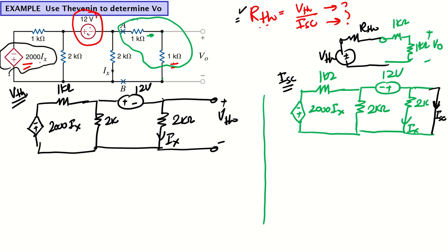Thevenin will always be the open circuit voltage. Current always flows through a short circuit. Like if you have an open circuit, current is zero. So we will make the load removal point a short circuit and find the current. Okay, now we have a simple circuit here. You can apply the different techniques, whichever you like, to analyze this circuit.